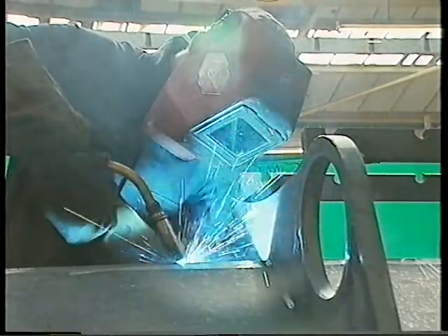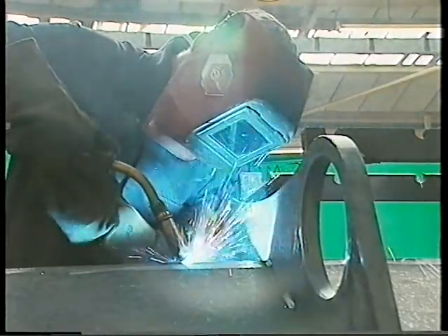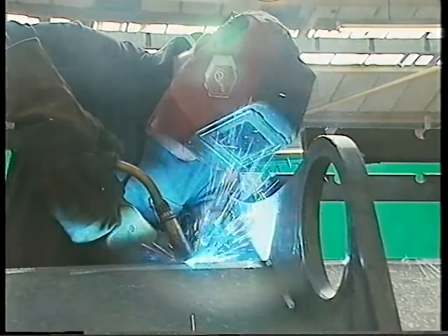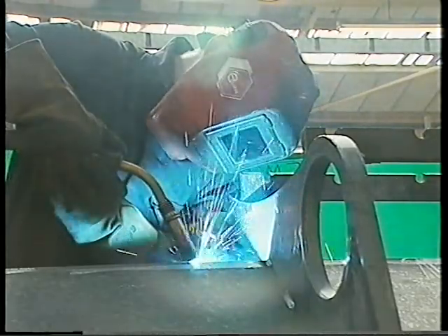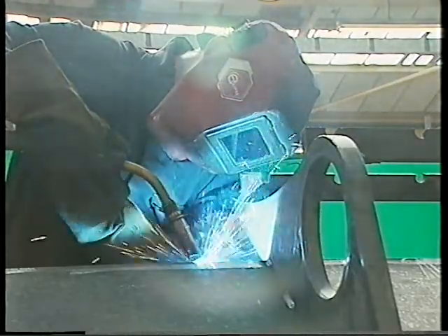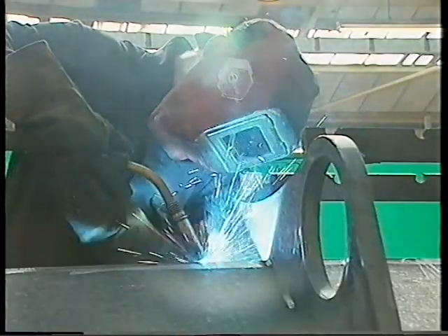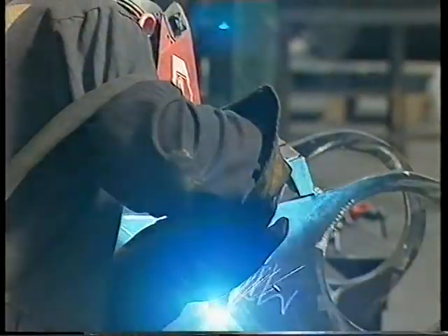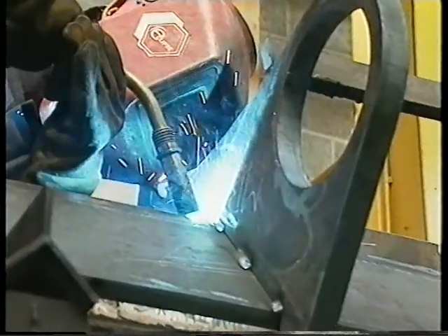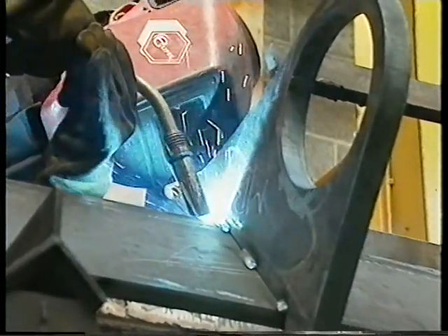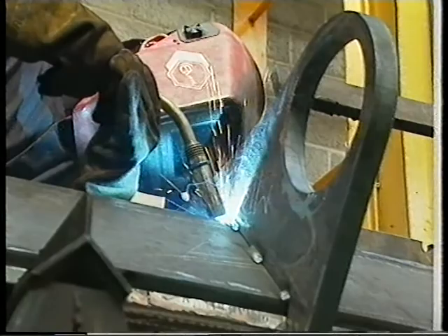Using the correct shielding gas in gas metal arc welding is essential in order to achieve the best quality weld. Shielding gas mixtures which contain argon, carbon dioxide and oxygen are designed for successful welding at all current levels and transfer modes, and are the ideal choice. But welding can be carried out using argon carbon dioxide mixes and even pure carbon dioxide.